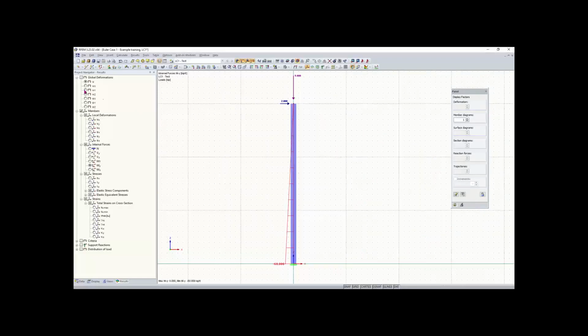And so also when you look at, we can take a look at our deformation in the x direction, 3.782. That's 3.782 inches. And now I just want to show you how this linear or first order calculation differs from a second order calculation.